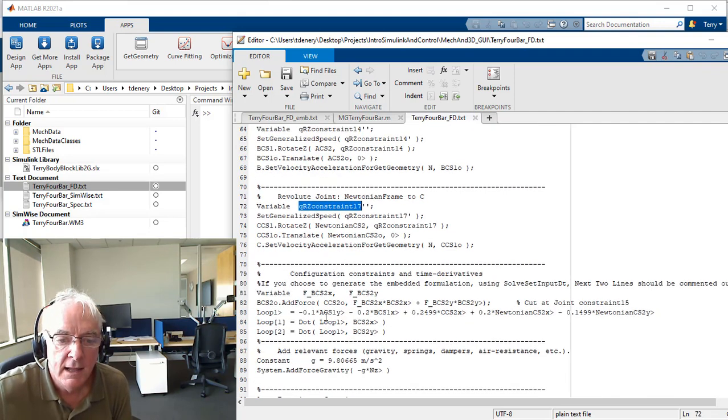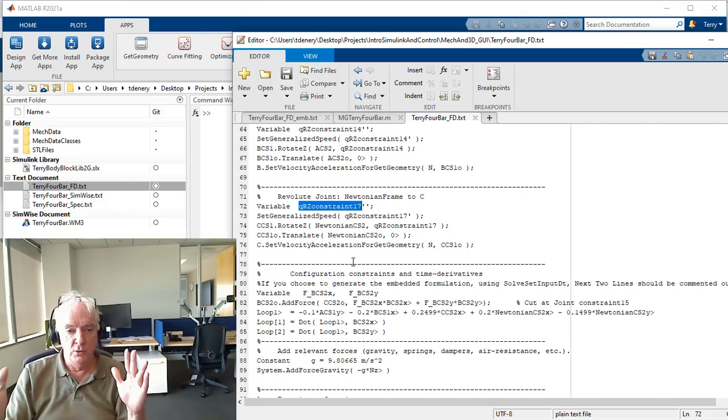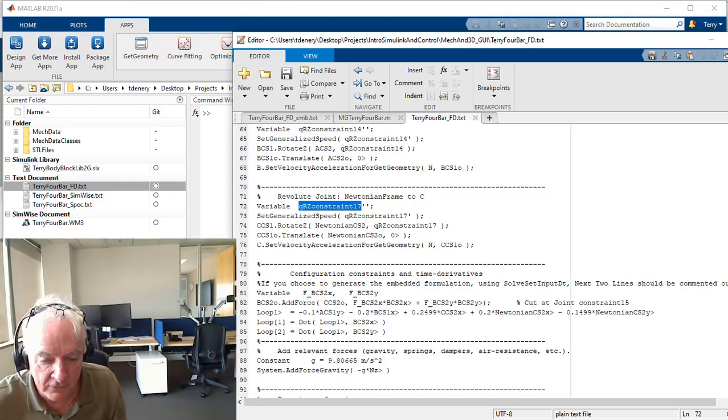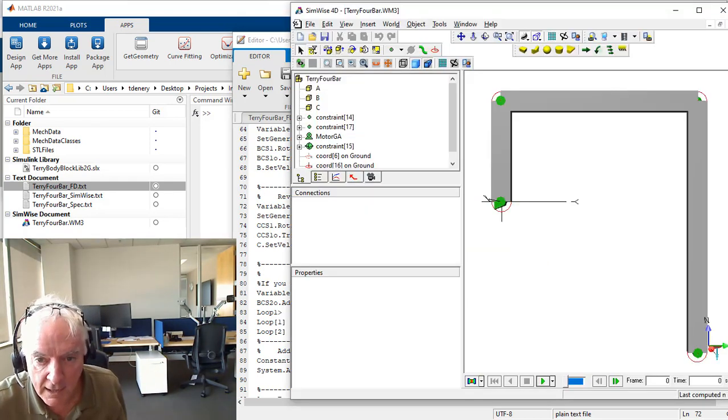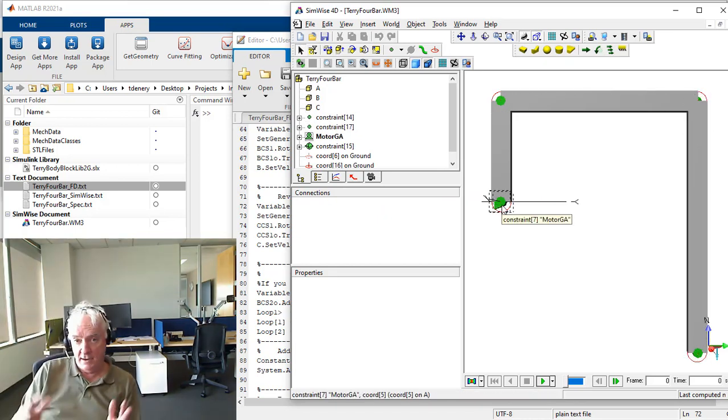The whole idea of why 4 joints can be reduced to 1 degree of freedom is that there is a mechanical loop connection. We see in our mechanical model that this goes from there to there, and then the ground connection takes it back, and that's why it's called a 4-bar linkage.